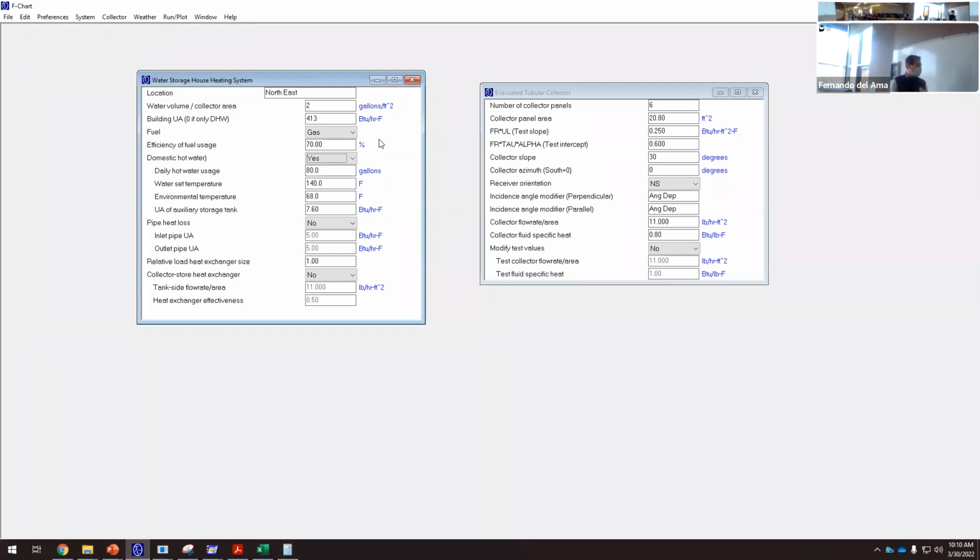You see what we have done? We have calculated the total heating load of the building, and then we have to divide by the temperature difference between indoor and outdoor. We can calculate this with the Excel file, or we can get this from Revit. In Revit, I showed you how to calculate the heating load. We need to know the temperature difference, indoor minus outdoor, and then we divide by it, and then we get the UA.